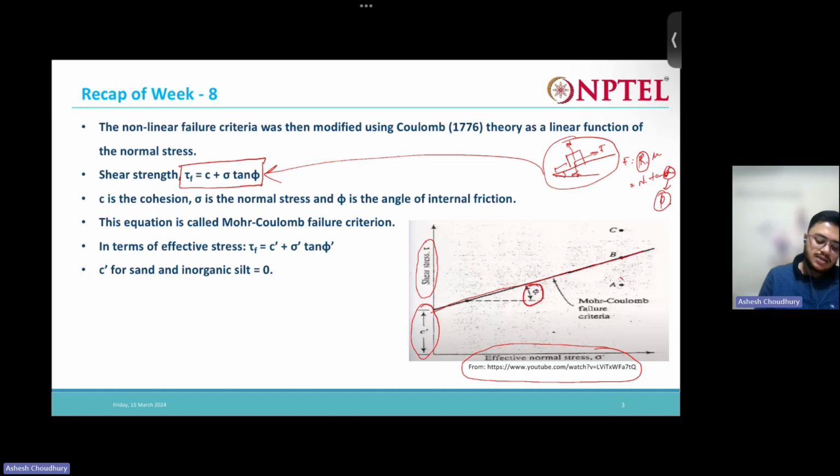All right. So here at the point A, if the shear stress and the effective normal stress at any plane falls below this failure envelope, that is at the point A, then we can safely say that the soil won't fail. Okay, and if it reaches the point B here, then it is at failure state, and this C is actually unachievable. We cannot have these stress combinations.